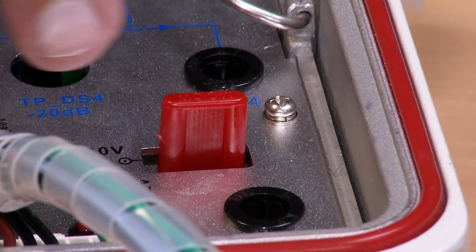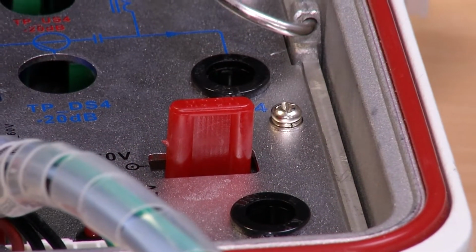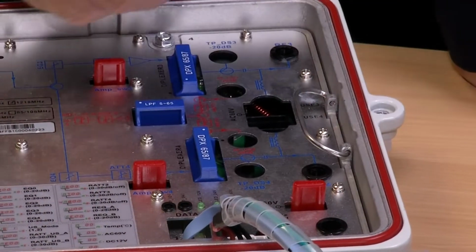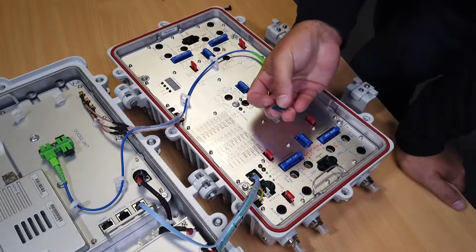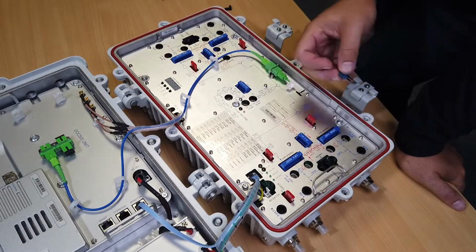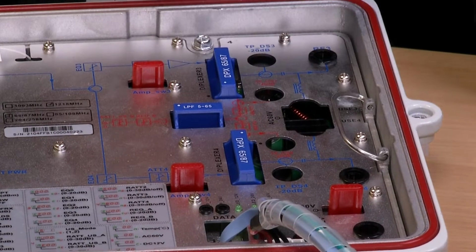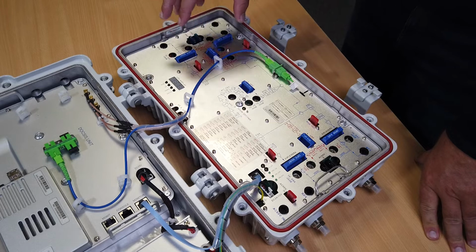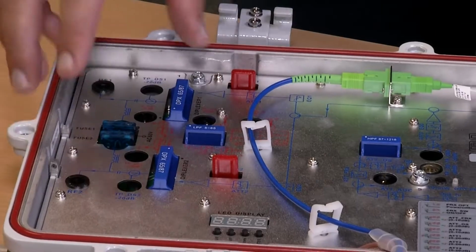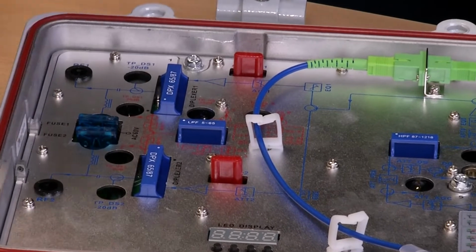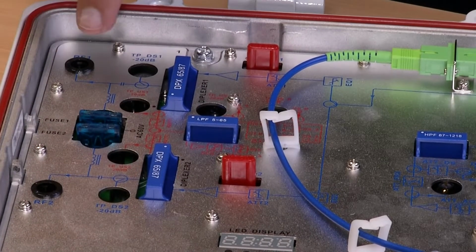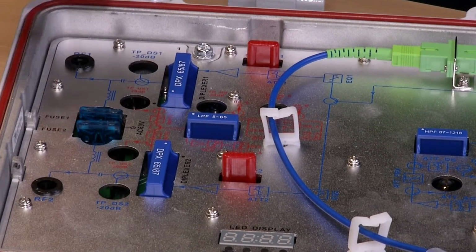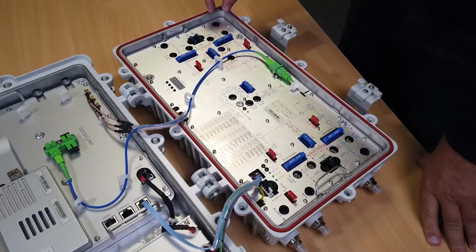This is where the shunt plugs in, activating the 60-volt supply. It can be plugged into each output separately. For safety's sake, there's also a fuse on each output, which allows 60 volts or up to 90 volts to be fed onto the outputs. On the other side, there's the same thing, like I showed you before, just simply mirrored. The two outputs again, for the second upstream. So these two outputs can be remotely attenuated in the event of faults.